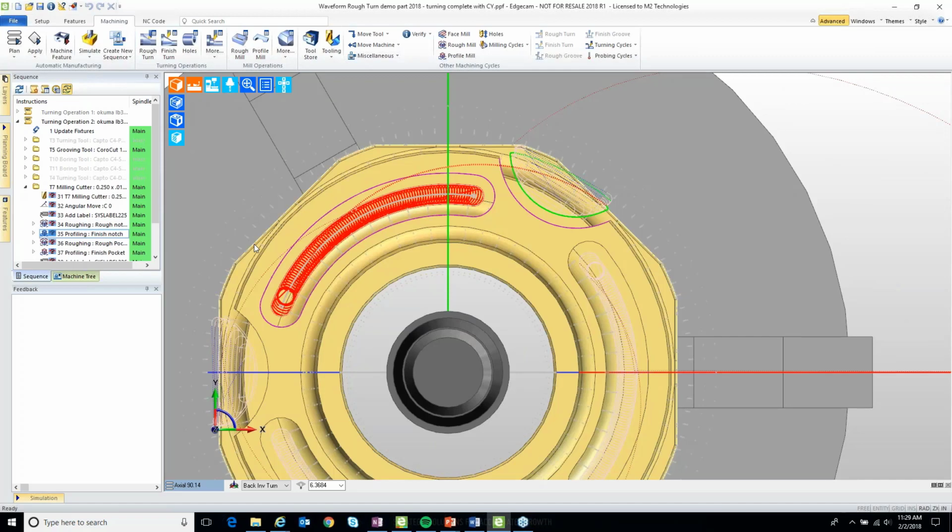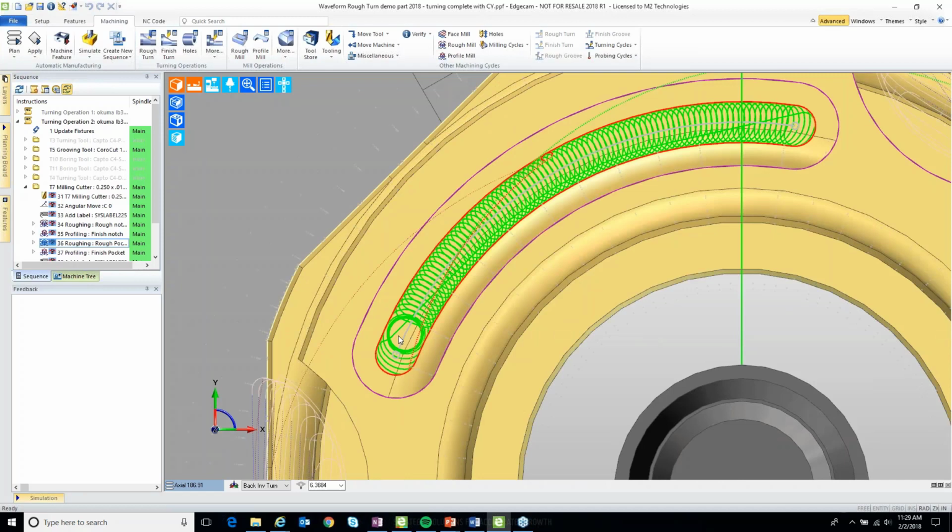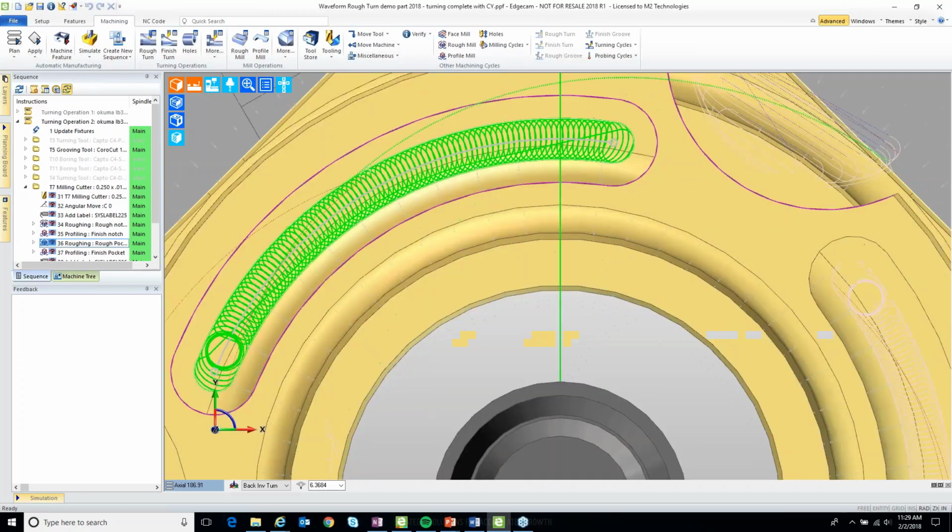Again, this is an application that we have done out in the real world, and with the limits of how many tools are on the turret, it was excellent to be able to helix down into this tight area and have a very efficient path that runs this tool right through the shape, machine the outside shape, and get it all done with a single tool.